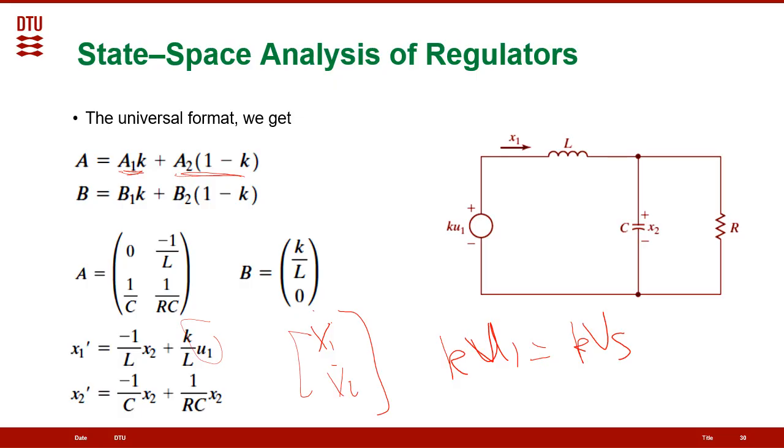So I will show you in a separate explanation how we can convert the state model to a transfer function, so that you can design, for example, a PID controller for your converter.